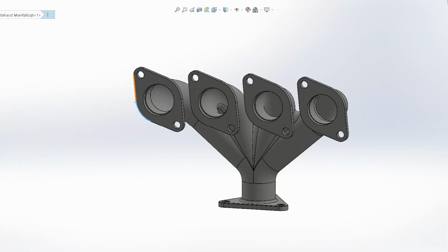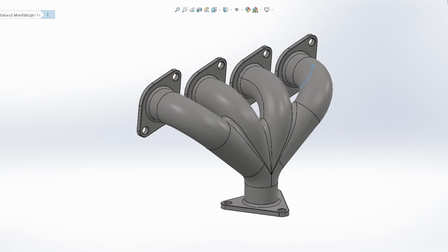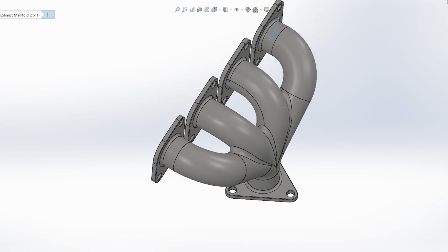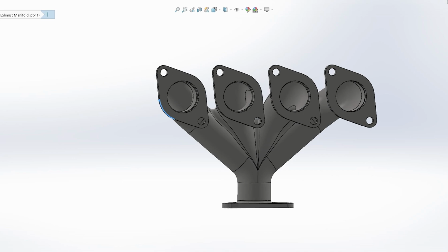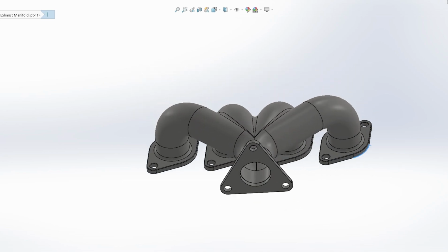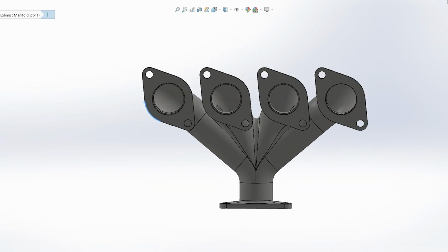Now, an exhaust manifold is a part of an engine that collects exhaust fumes generated by the internal combustion engine. It conveys them towards a catalytic converter or turbocharger. Firstly, you need to note that the forces acting on the exhaust manifold during operation are immense. And let's not forget the high temperature that it absorbs from the gases. Now, with CFD, we're able to analyze which material is better for casting when producing our exhaust manifold.